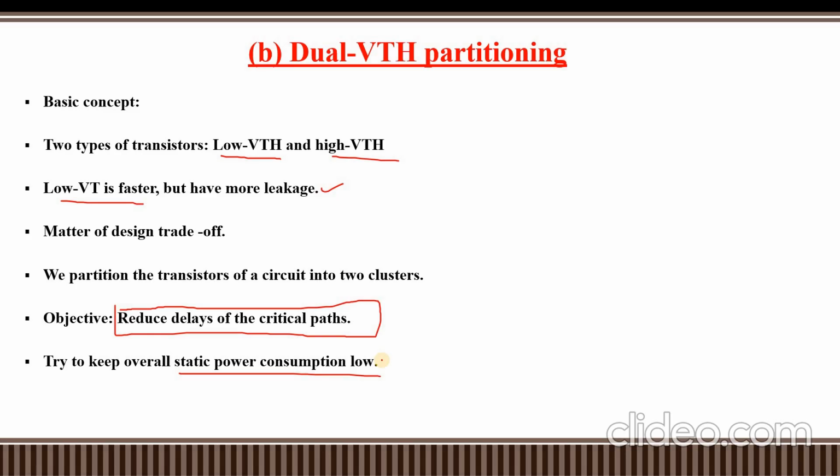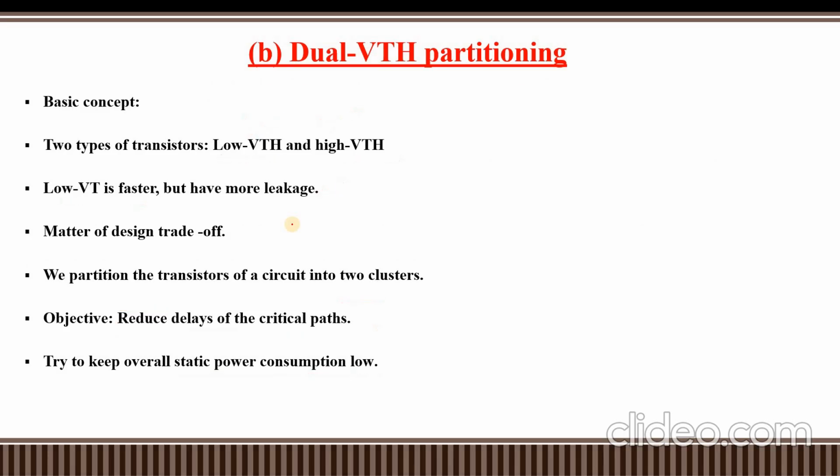In dual VTH partitioning, we partition the transistors into low threshold voltage transistors and high threshold voltage transistors. Low threshold has more leakage current. So finally it can reduce the delay of critical paths, and it can keep the static power consumption low. This is another technique to reduce the static power.